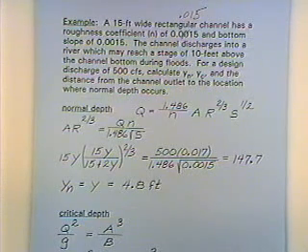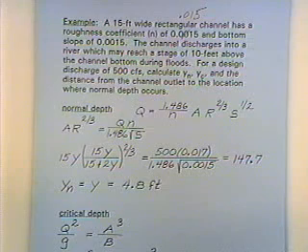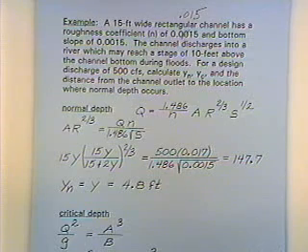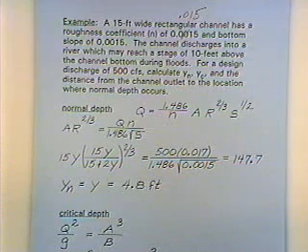Now, if you get far enough away from the river, you can use Manning's equation. It's a prismatic concrete channel, a constant bottom slope of 0.0015, a constant bottom width, a constant rectangular channel section. So we can use Manning's equation to compute the depth. However, the backwater effects from the river into which the channel is discharging cause a non-uniform flow situation.